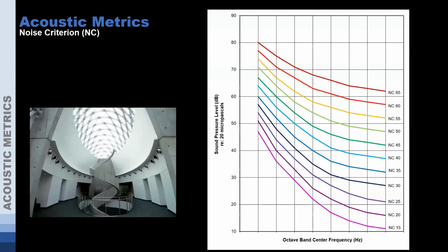So we talked earlier about what decibels are and how they're logarithmic, and you probably hear things measured in decibels. Another thing that we look at, especially in architectural acoustics, is what's called noise criterion, or NC curves. These were established for rating indoor noise from things like your air conditioning equipment or other building equipment. So it's another way that we can look at this. You can start to see that these curves, in the lower frequencies, are much higher, and then they drop off as you get to these lower levels.